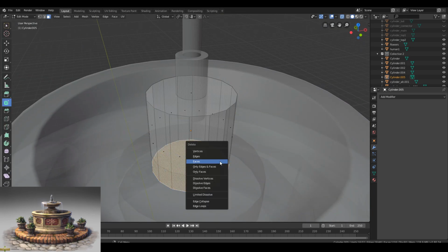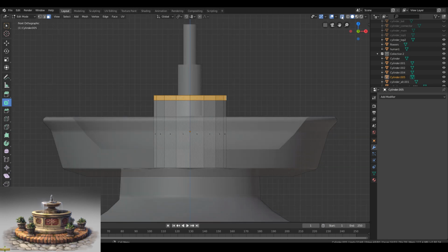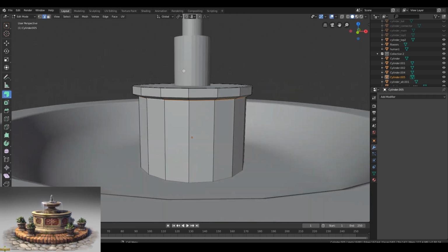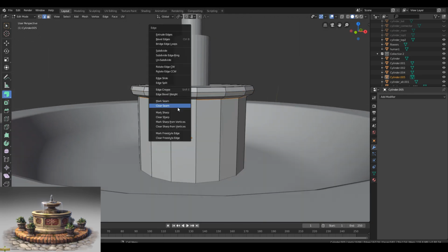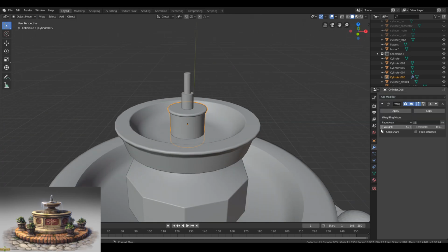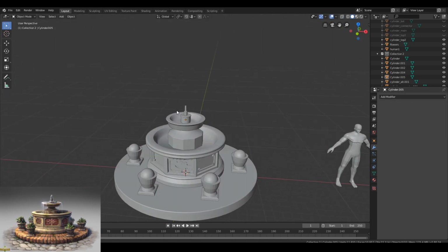Create a cylinder on which we put an additional edge on the top and use extrude on the loop created at the top. We add small details, remembering that this element will be hardly visible, so there is no point in adding large geometry here, as it will affect performance. We apply weighted normals and start texturing the object.